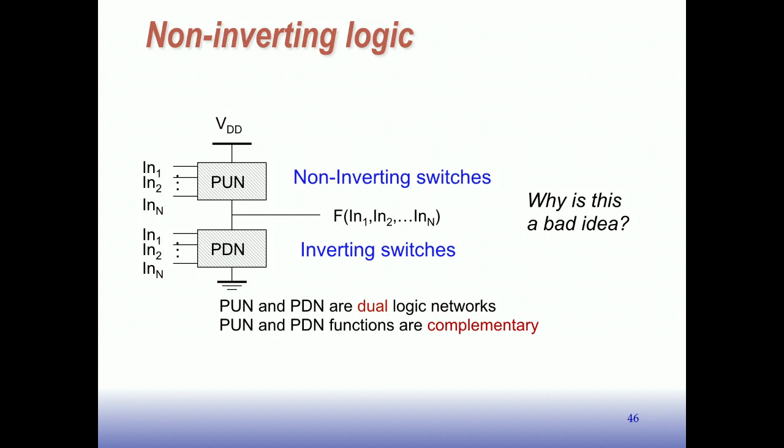Right, so if A and B are both 0, well, let's see. Okay, if this were to work, then out would be a 1 here. And then in every other case, one of these things would be on. They'd be a 0 here, so you get zeros here. And that would look like an AND.